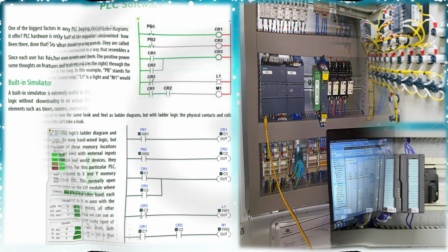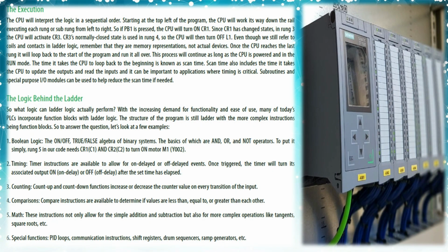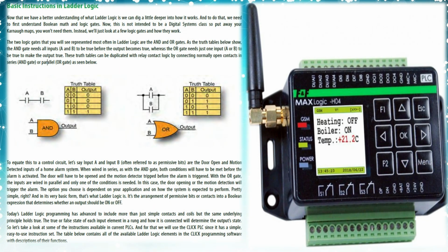CPU module has a central processor, ROM and RAM memory. ROM memory includes an operating system, drivers, and application programs. RAM memory is used to store programs and data. CPU is the brain of PLC with an octal or hexadecimal microprocessor. Being a microprocessor-based CPU, it replaces timers, relays, and counters. Two types of processors, a single bit or word processor, can be incorporated with a PLC. 1-bit processor is used to perform logic functions. Word processors are used for processing text, numerical data, controlling and recording data.